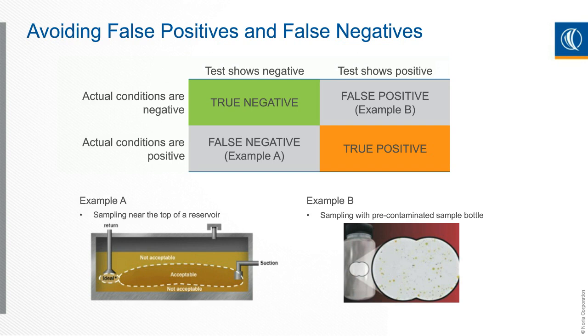So you need to make sure you use clean bottles or ultra clean. There's ratings of bottles and how clean they are, and that's going to be dependent on what the sensitivity is of your machine and the analysis you're trying to get. So knowing the potential cleanliness of not just the bottle, but the overall equipment you're using to take that sample is going to potentially affect the results. So you want to be aware of that and not have a false positive.